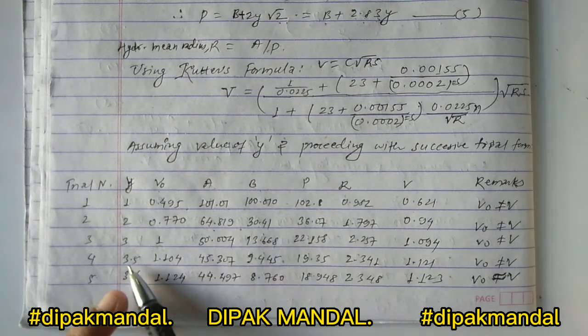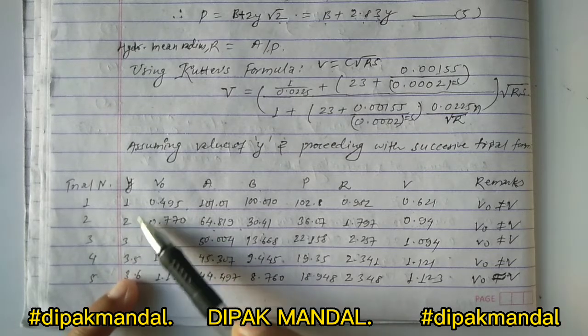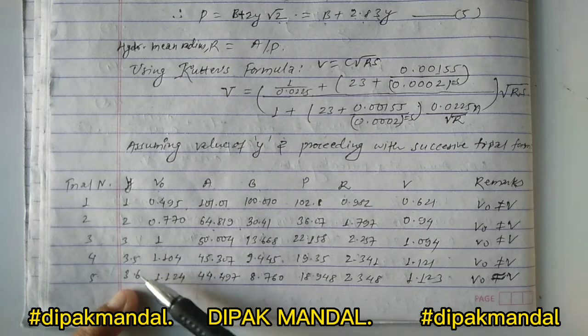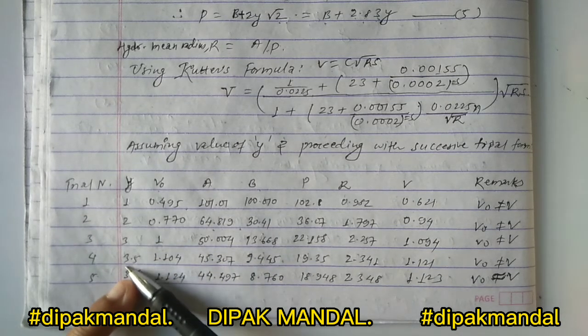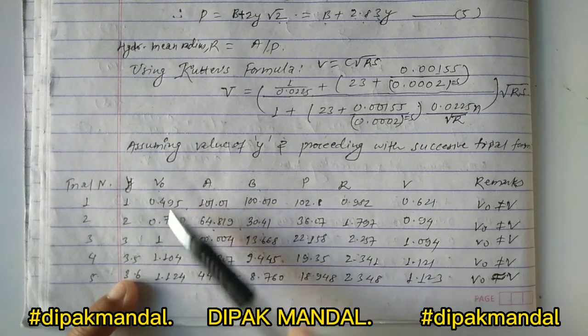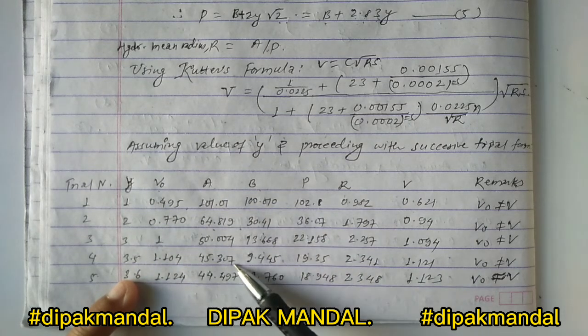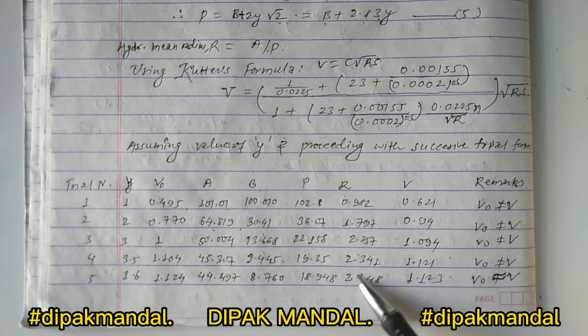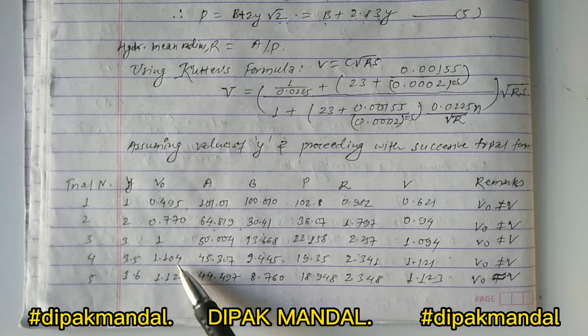So in trial number 4 we have to take the value of Y equal to 3.5. You can take this value by increasing 1, or you can take 0.5. It's your choice. And in trial number 4 we have to take the value of 3.5. Then the V naught equal to 1.104, A equal to 45.307, B equal to 9.4, P equal to 9.3, R equal to 2.3, V equal to 1.12, and this is also 1.121, and this is 1.104, so we have matchable value.